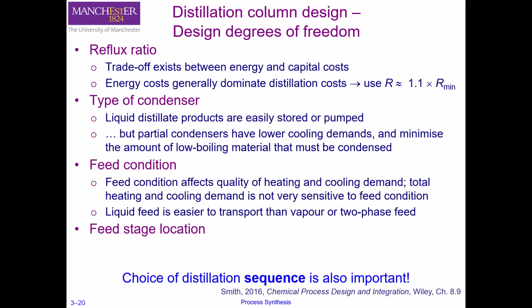The feed condition is also another important design degree of freedom. So the question is, should the feed be a vapor, a liquid, or something in between? That is, should it be subcooled or superheated? The condition of the feed affects the enthalpy of the material entering the column and clearly affects the overall energy balance of the column.